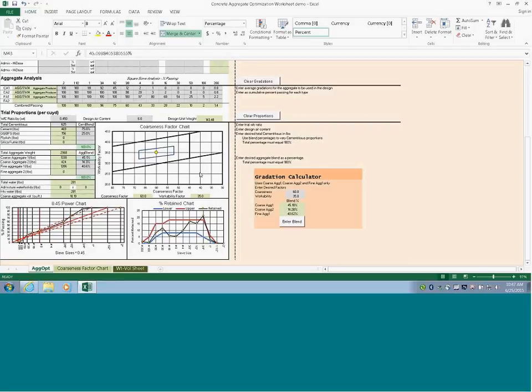Yeah. But no, we're not using a cap on anything because there's a minimum and max for cement. But no, we're not really looking at it that way. That isn't the issue. The properties of the mix are the issue. If you're getting real high like that, the producer and PennDOT ought to be looking at the amount of cementitious in the mix and see where you are there. Maybe able to reduce the amount of cementitious and still get the strengths you need with low shrinkages and low permeability. So.